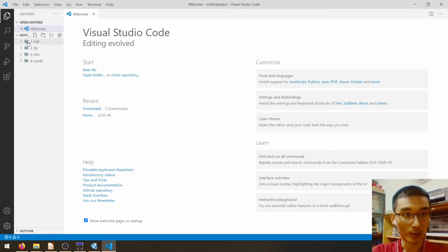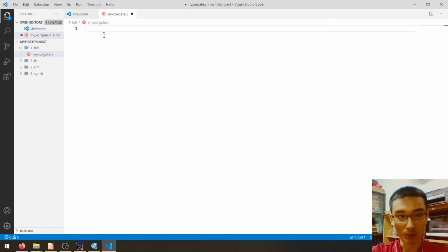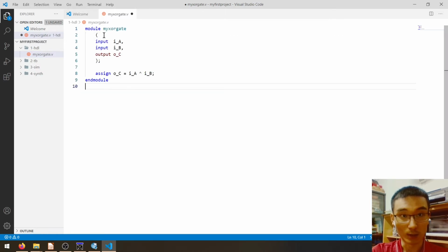To start writing HDL, click on this folder and then click New File. And let's call it my circuit. Since I am using Verilog, the extension will be .v. Since this series of videos is more about the workflow, I won't waste your time watching me typing the code. So let's paste the code here.